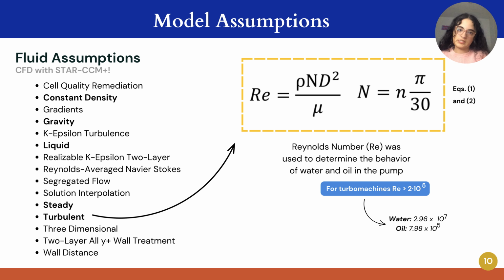The fluid assumptions of the model listed on the left are the ones used in the CFD simulation with Star CCM+, the most relevant being the constant density, the gravity, the liquid fluid, the steady state, and the turbulent fluid.